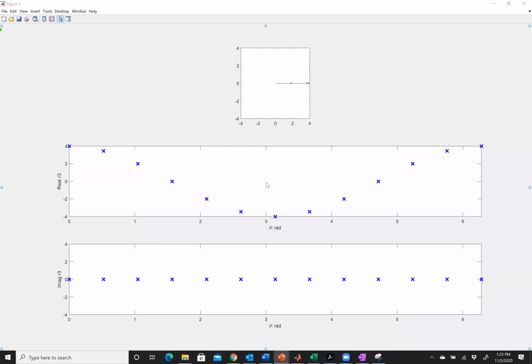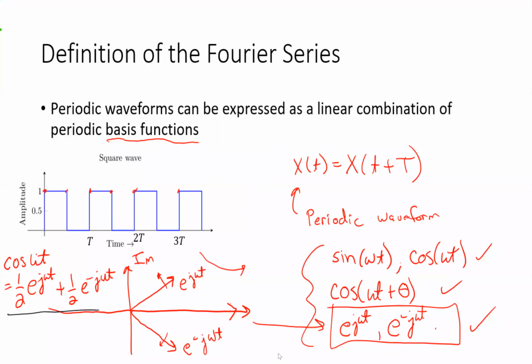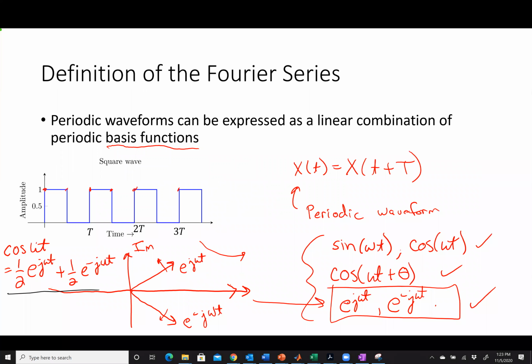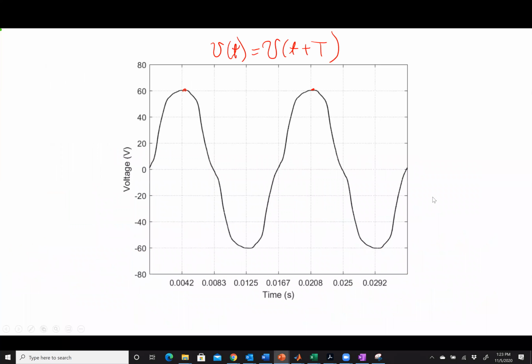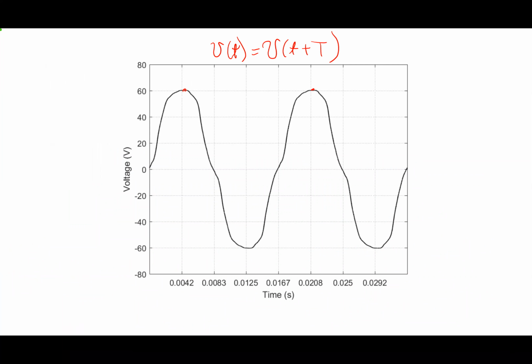We're going to look at those forms of the series again. We've got these three different ways of thinking about any kind of periodic waveform. I gave this example before. This is a scaled down version of the voltage at the wall here in EPIC. You can tell that it's periodic. It looks like it's repeating, at 60 hertz as the fundamental frequency, which means it's got a period of about 16.67 milliseconds.